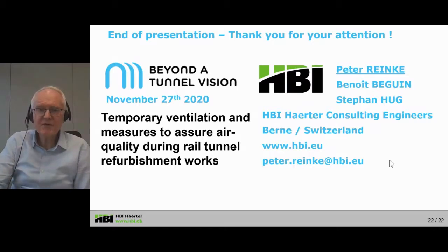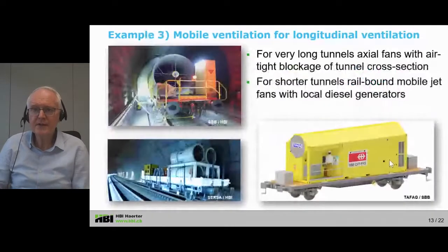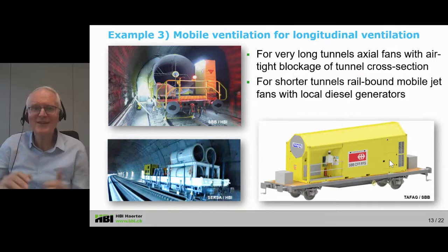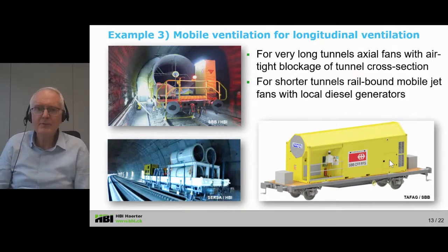Well, of course, those jet fans, maybe I go quickly back, those jet fans, they work only if you keep them individually apart. So you would need to place a certain distance between each of, for example, this yellow car shown at the bottom right. And then sort of there is a superposition of these different fans. Maybe this answer is too simple, or it depends on the individual case or individual problem. But in principle, you can add on the power of different fans to create as well sufficient airflow in very long tunnels, for example.